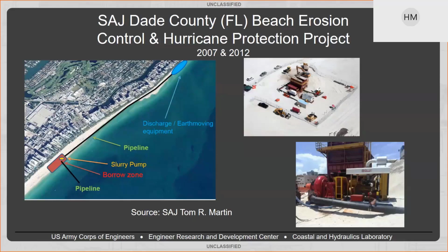There's a little RSM project that Portland District did that looked at the unit cost savings for different ways of managing dredge material placement for nearshore placement. We were looking at more of the operational savings in terms of hauling this nice clean sand to deep water sites versus spending a little bit more time to place it nearshore. It turned out that we actually saved money by going nearshore because it's a slightly closer location. So it's an increment on the overall operational cost savings, but that's on the operational side.